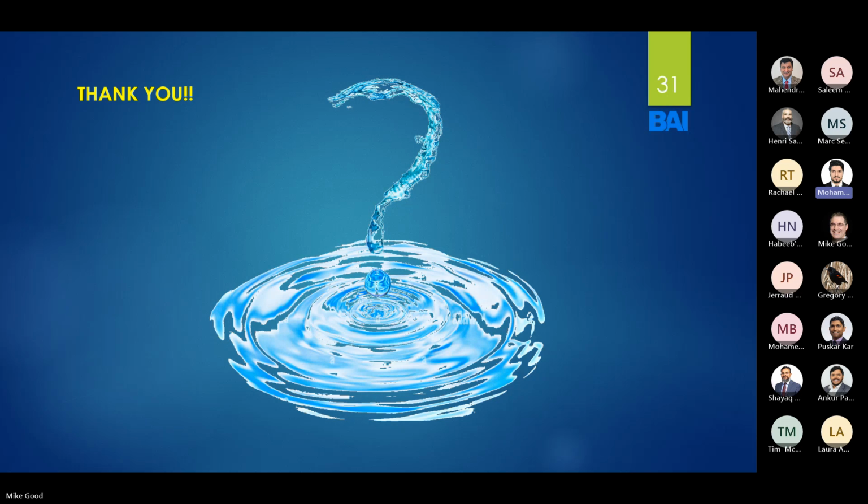We would design it as a pier, and according to that we would give all those moments and actual forces to the pile. So even if there is no soil, that loading could be carried by the pile alone. At the end, it would be socketed into the soil at the very bottom. That would also be determined by the geotech, so they can see where we can go, what is the safe zone for the piles. So all the forces, horizontal and vertical, from the earthquake would be given to the piles, and they would be designed such that there is no soil confining those piles. So basically, they're designed as columns. Exactly.